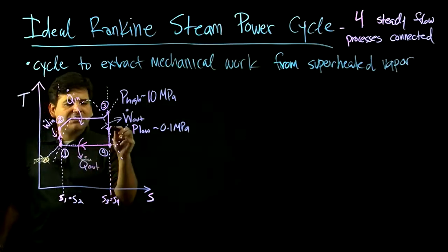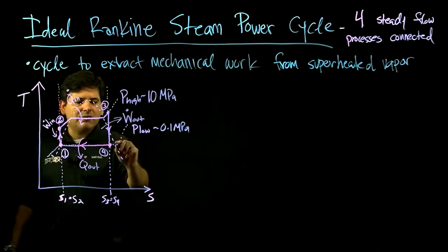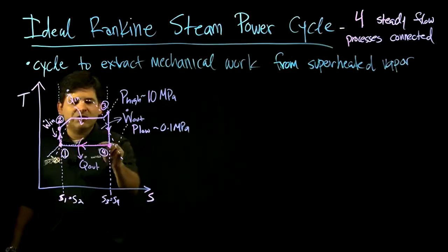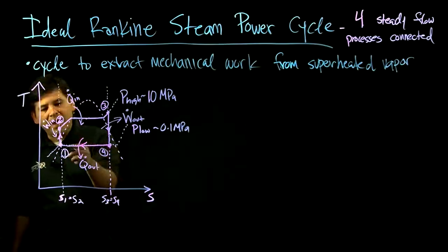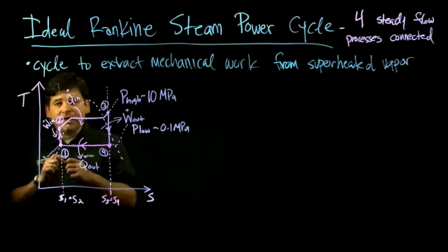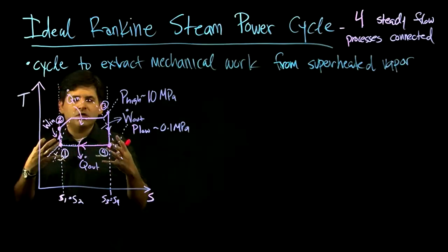In this case, after you get the mechanical work from a turbine, you end up with lower enthalpy, but it's still not the original state. So you have to get back to the original state, there's this heat exhaustion step to go from state 4 back to the original state. And in a Rankine cycle, this is the cooling towers, where you lose energy.